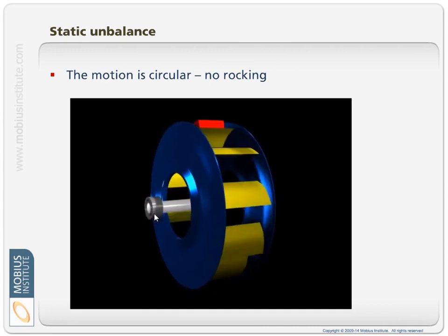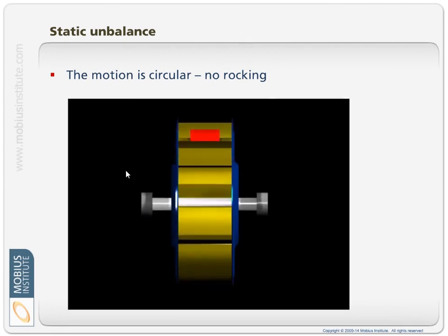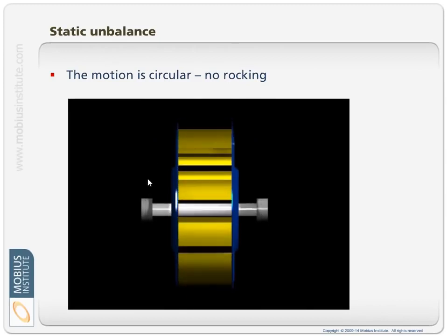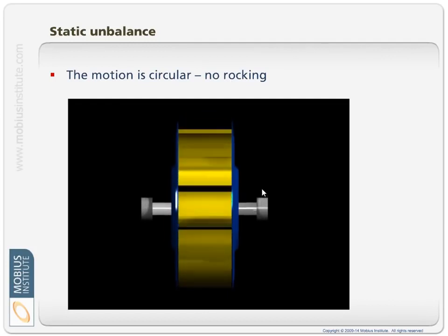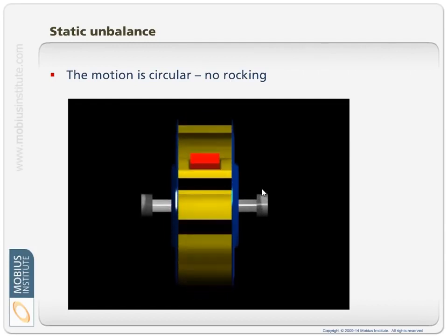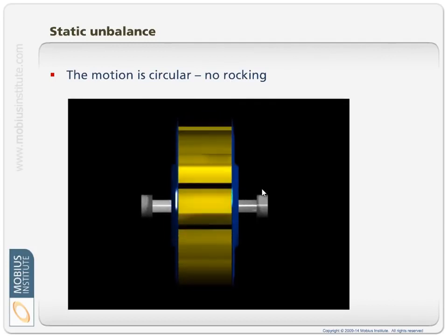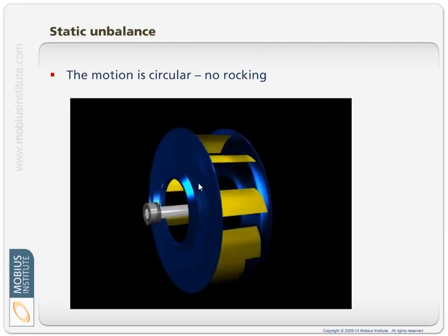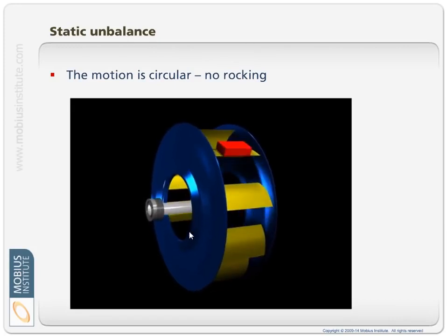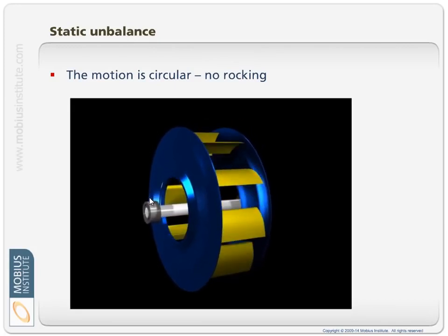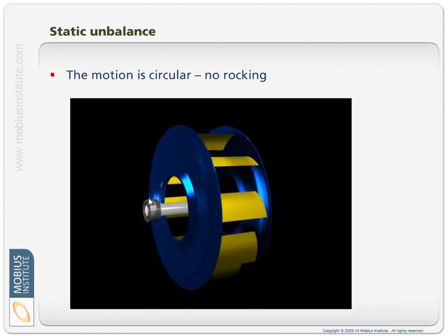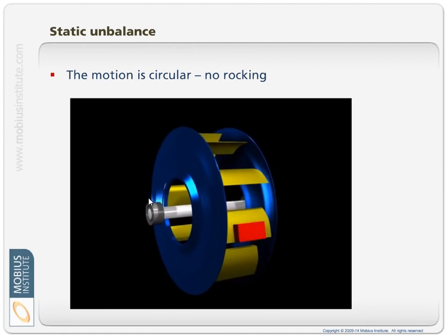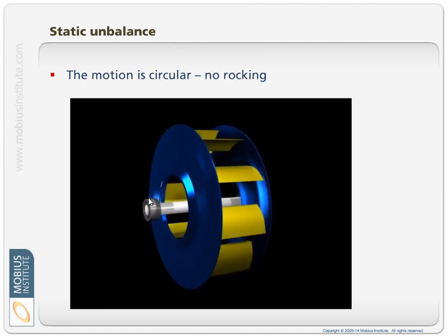So, that tells us a lot. From here, if we could take a phase reading, we measure vibration here, and we measure vibration here, and we see whether it's going up together, down together, up together, down together. If we compared the vibration vertically here to horizontal, we would see that they're both going up and down, but there's a quarter of a rotation delay between the two.